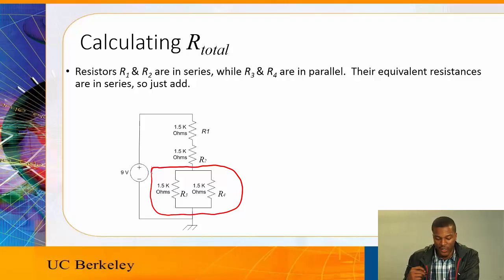Well, let's find out. If a current flows through to this branch, there will be some that breaks off there and some that breaks there. Also, we can say that this point is one node and this point is one node. Because these two are connected at both tops and bottoms, at two nodes, they're in parallel.